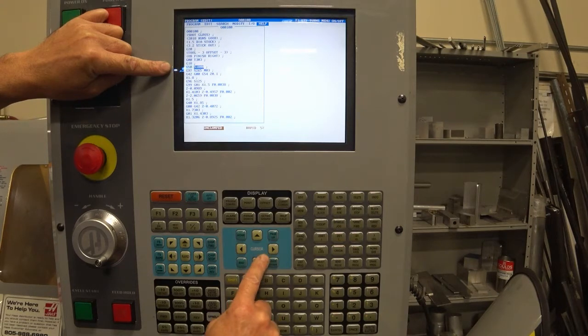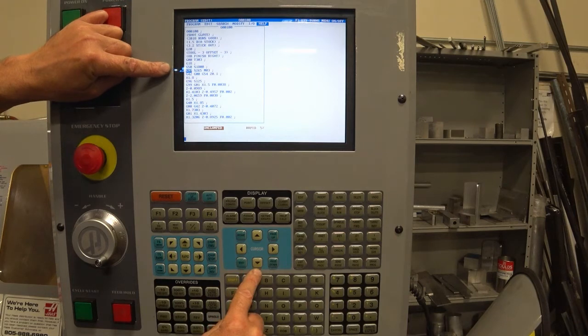You should never run a program without a G50 line present, as without it, the spindle will accelerate to the maximum capable of the machine when the tool is at X0. This maximum value would create centrifugal forces that would exceed the lathe chuck, launching the material into the cabinet and potentially through the door into the operator. It is very dangerous and should never be done.